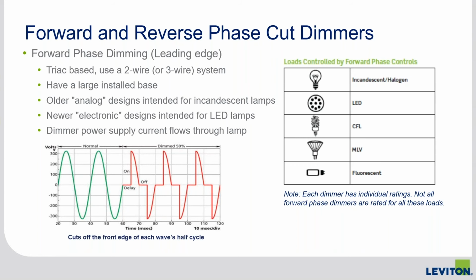So you really have to keep in mind that if you're using low voltage lighting, you check what type the transformer is. Some other examples of this might be tape lighting, under cabinet lighting. Some outdoor lighting is low voltage. So it's just always important to check and make sure that you have the right load for the right dimmer for the right type of load.